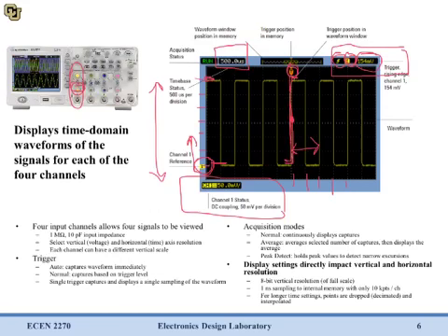It's going to try and keep this part of the waveform, or this element here, constant in time and always plot it right there. Really the best way to tell how this works is to go play with the scope and see how various trigger options affect how it's displayed. But in general, you'll want your trigger set to about half the value of your waveform, so somewhere between the min and the max values.